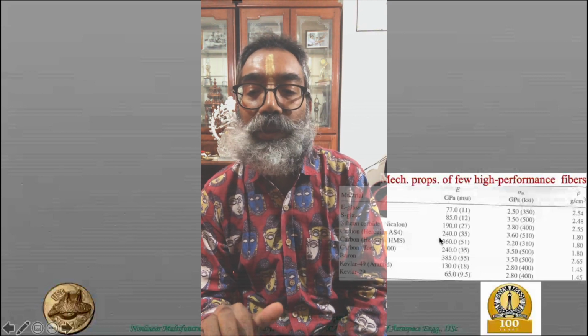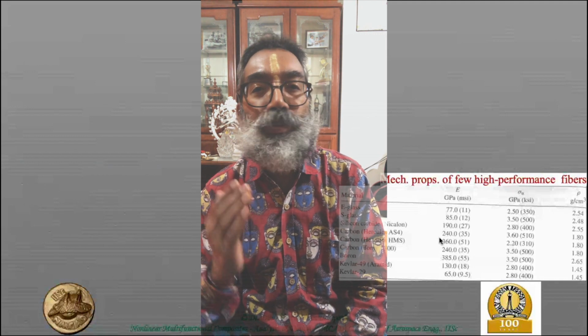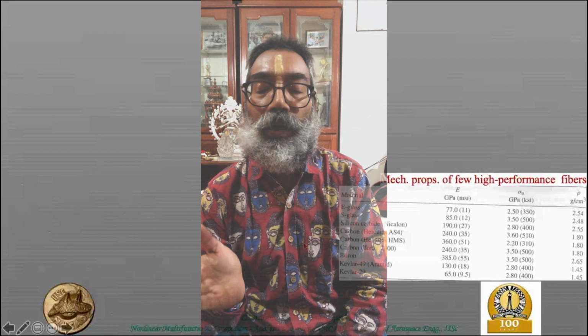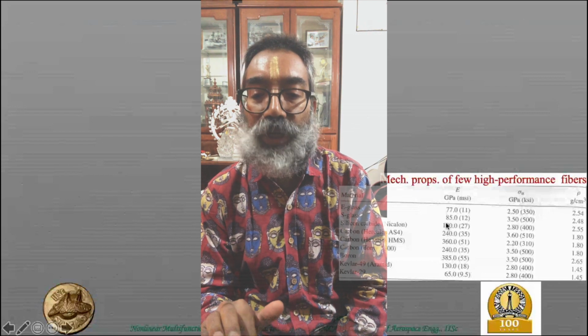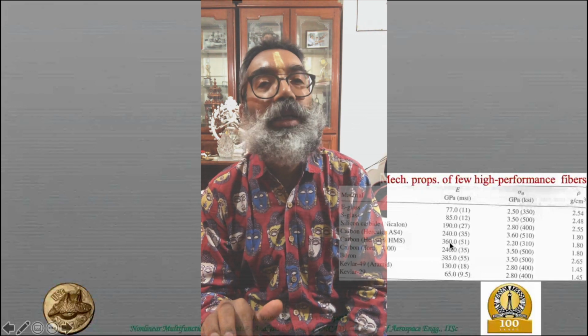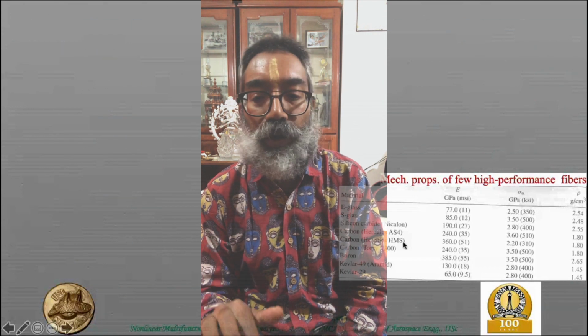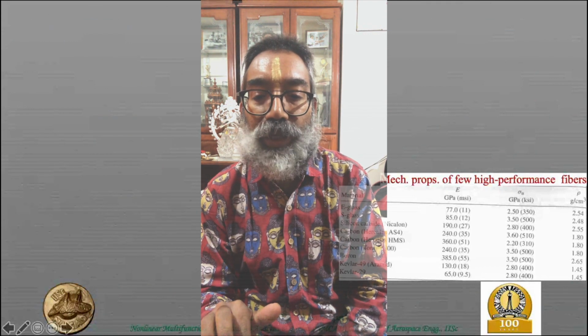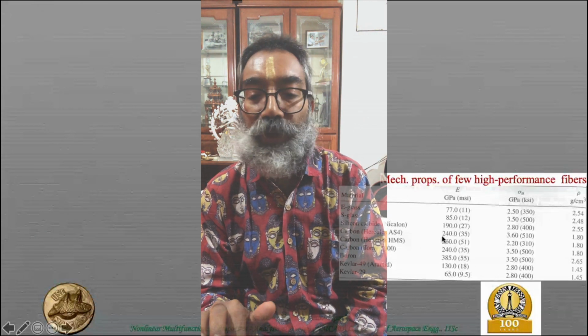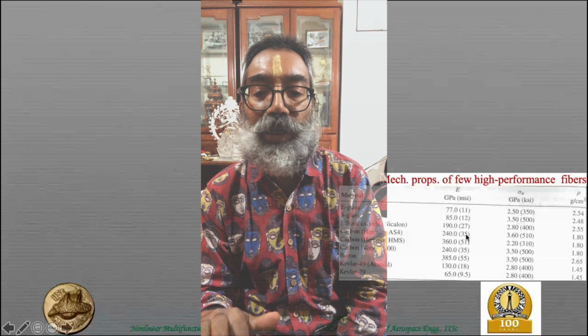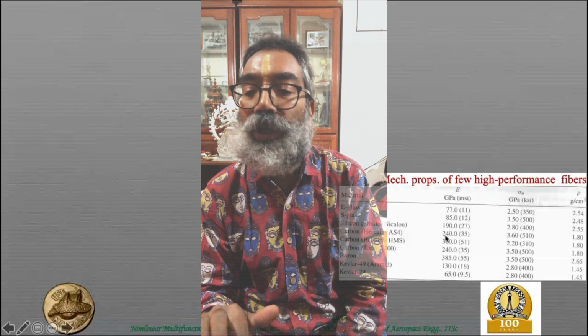Because density is not different, the only determining factor for the specific performance index, whether in stability or in stiffness, including natural frequency dynamics, is E alone, and therefore a larger E would be better. Therefore something like the HMS, which Hercules is the company that makes it, Toray being a Japanese company which makes it, etc. Amoco is another company in the US which makes carbon fibers on a large scale.